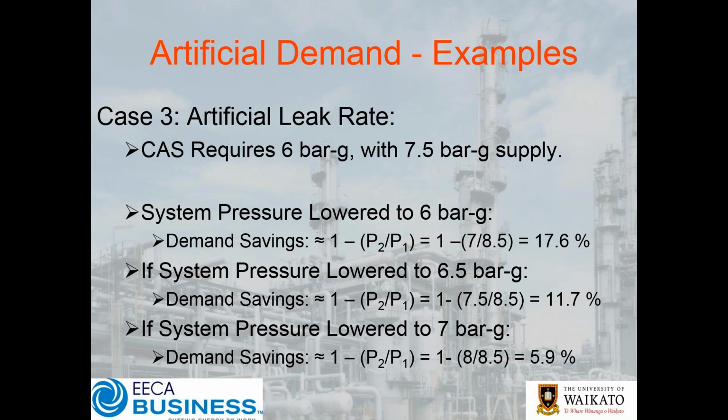Okay, so what I want you to think about for a minute here is, if you've got that 1.5 bar increase in system pressure to compensate for other deficiencies, it means that every bit of use across your site, and especially your leaks, are losing that much more, i.e. 17%. Okay, now if you drop to 6.5 bar, you're now down to 11%.